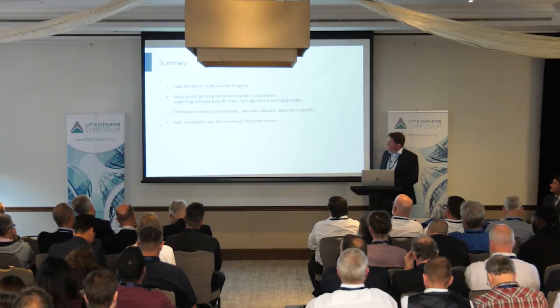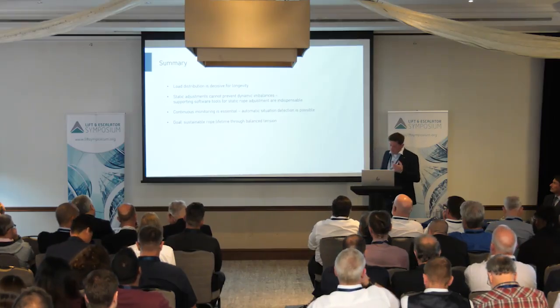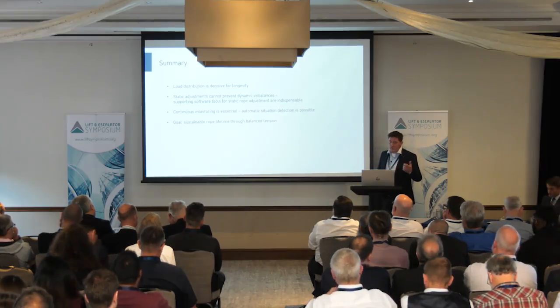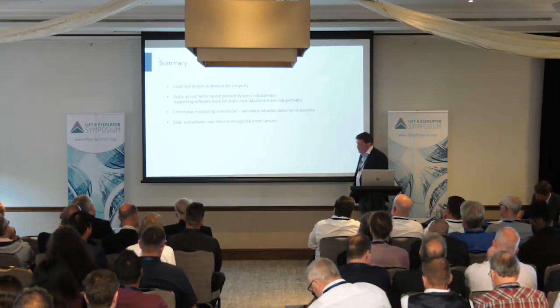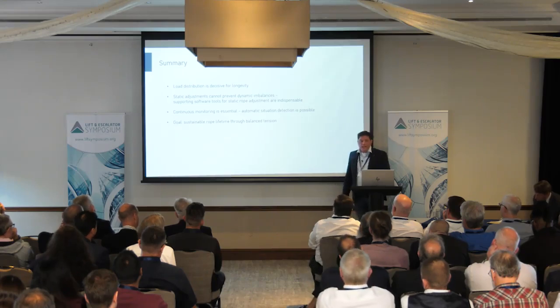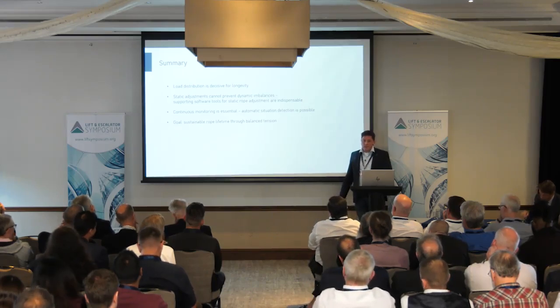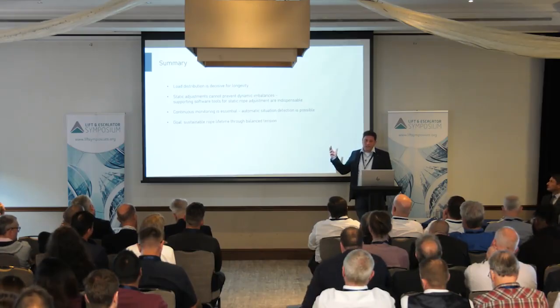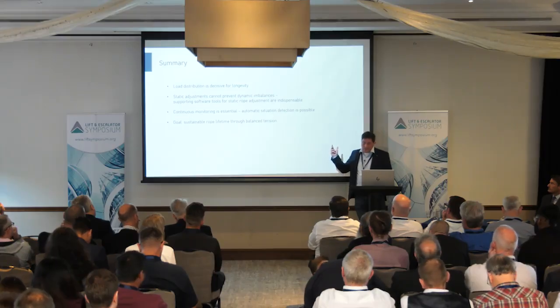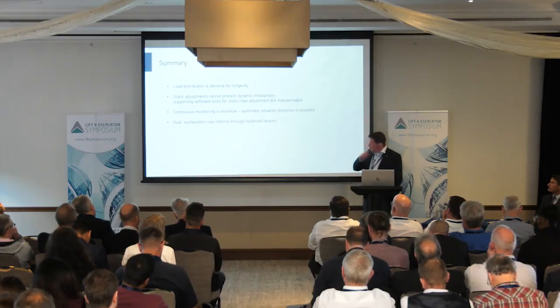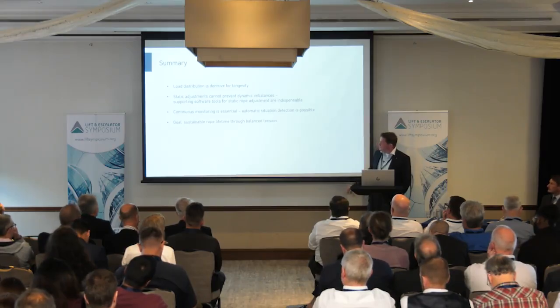So load or the tensioning of ropes, as I explained in the beginning or showed this formula, is really one of the key elements for the rope lifetime. You have seen 40% increase of rope lifetime, so it's really a huge factor, especially with high installations. You can save tons of money with that, depending if you are the service provider or the owner of the lifts.